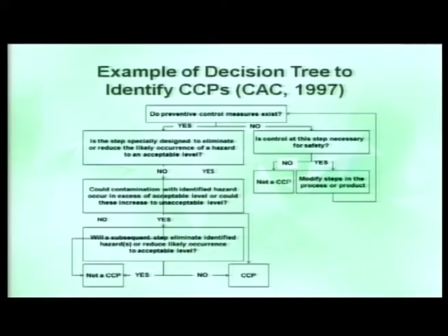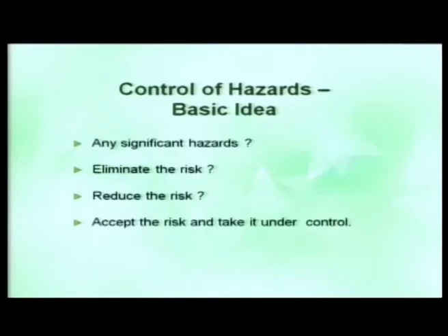Now to understand it, let me give you one example, the example of a dairy industry. If you have to make a poly pouch of milk, what is the process we do? We take the milk, it is put in the plate chillers and it goes through different sections, first pre-chilling, then it goes to a pasteurizer. That is, the pasteurization is carried out at a certain temperature, let's say 71 degrees for 30 seconds, and then it is again immediately chilled.